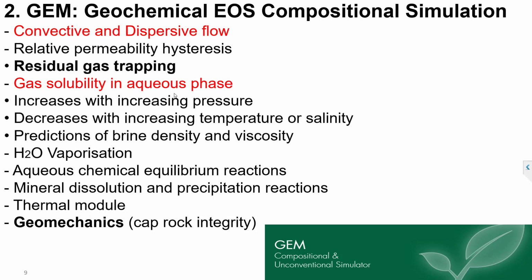The aqueous phase comes with related phenomena such as solubility increasing with increasing pressure and decreasing with increasing temperature or salinity, as well as a reduction of brine density and a viscosity change as a function of the amount of CO2 that gets dissolved into the water.